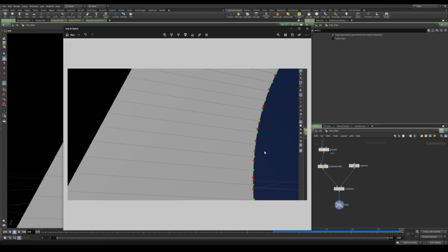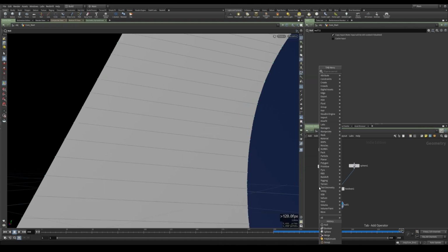And there's actually a very quick way to delete those points. Here I marked with green all the points that I want to keep, and in red the points that are generated by the boolean. Now, if we look on the mesh, the green points are always connected to 3 other points. They have one connection to the other side by this edge, and 2 connections on the same side. On the other end, the red points are not connected to the other side, so they are connected to only 2 other points on the mesh. And we can use this information in VEX to tell Houdini to delete all the points that have less than 3 connections. So let's see how to do it within a point wrangle.